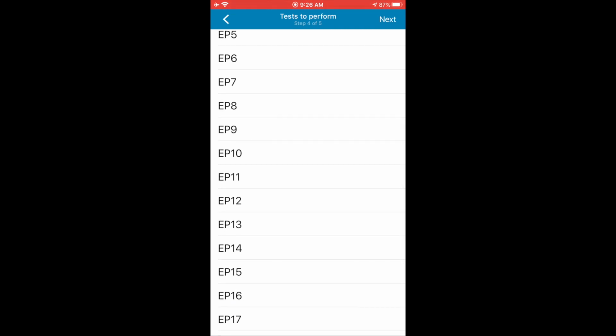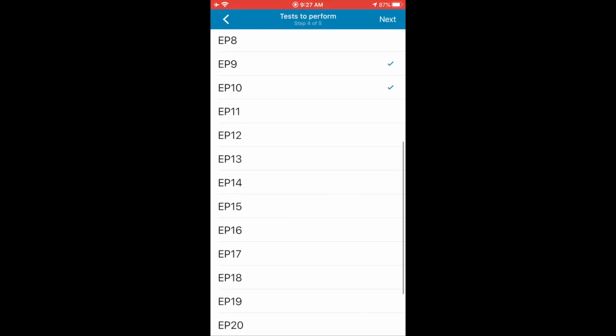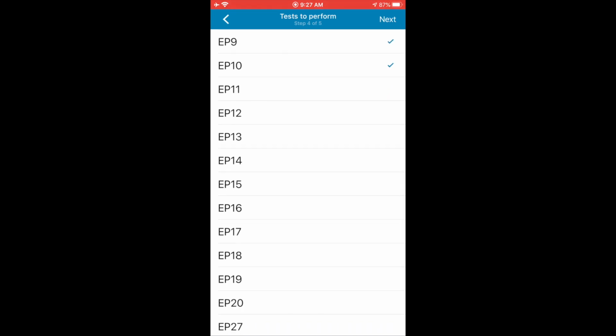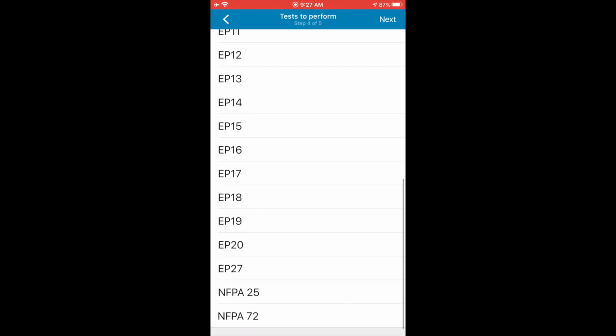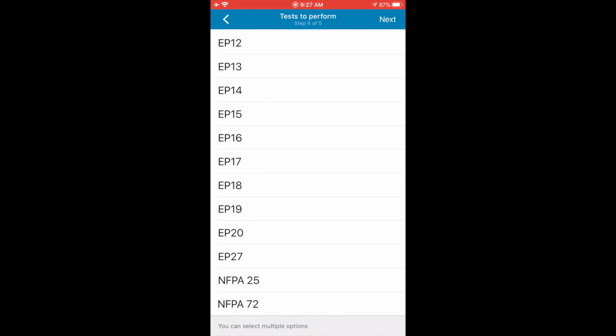I am going to choose EP9 because I am going to do a quarterly main drain test for this particular customer. I'm going to choose EP10 because I need to do my fire department connections, right? I'm not going to choose EP11 because I'm not doing a full flow annual fire pump test. And EP17, I'm not going to choose that either because I don't have any fire hoses.